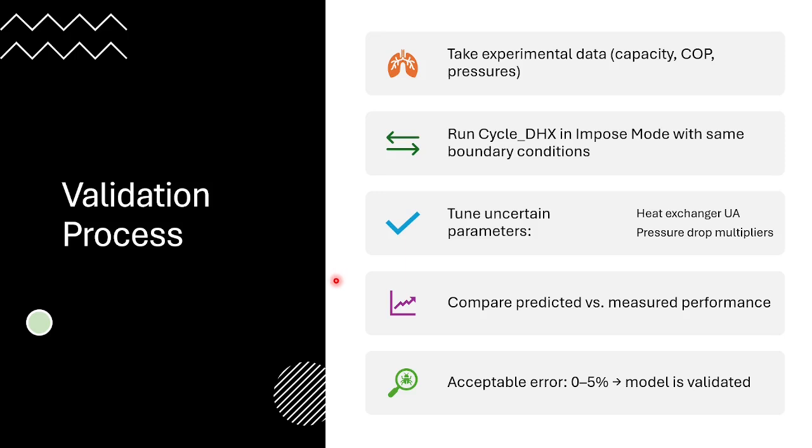The process of validation goes like this. We first gather the experimental baseline data, in our case for R134A, which is a favorite medium pressure refrigerant. Then we run the simulation with the same input conditions and compare the results such as saturation temperatures of evaporator and condenser, temperature and pressure state points, cooling capacity, compressor work and COP, etc. If they match closely, the model is validated.